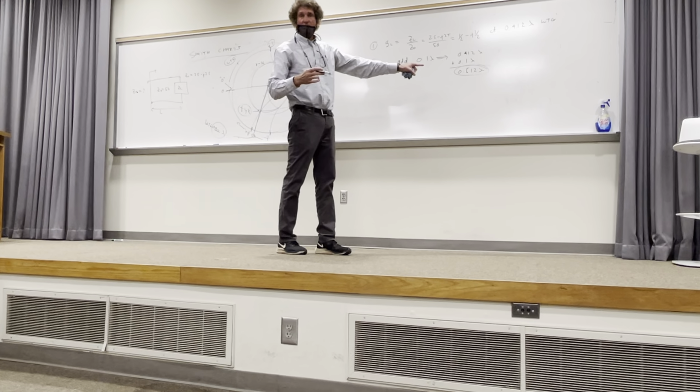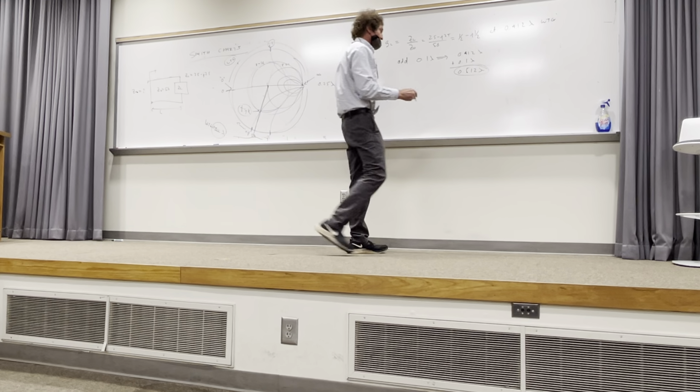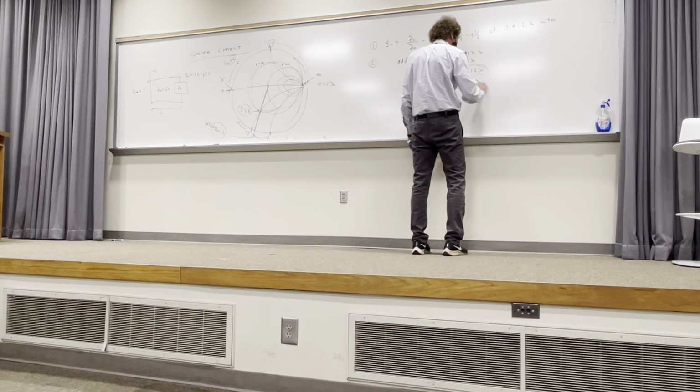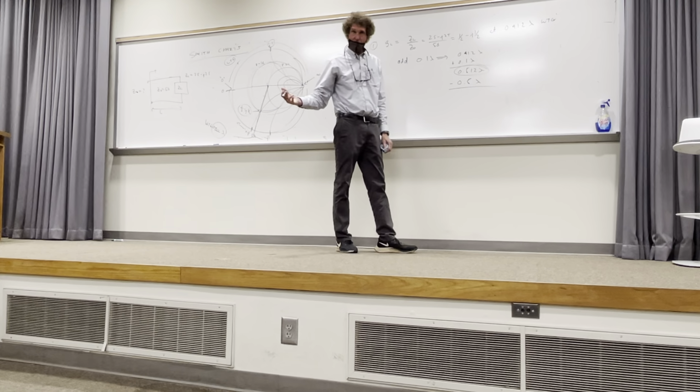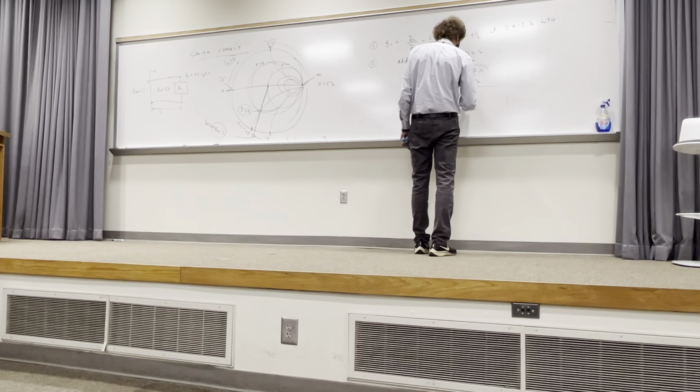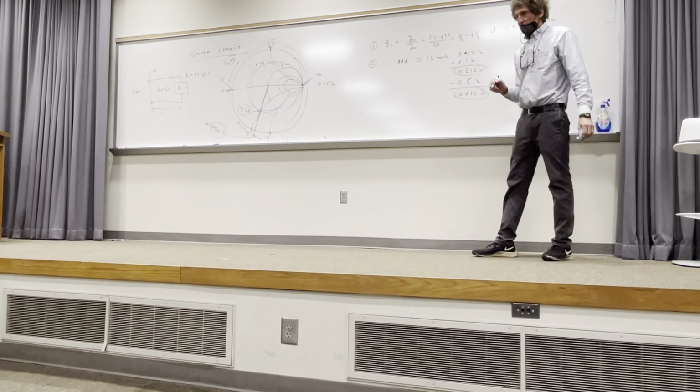So anytime you have a value after you added any distance from the load that is greater than a half wavelength, you subtract off the number of half wavelengths required to get this between 0 and 0.5. So now I simply subtract off 0.5 wavelengths. That would be 1 half wavelength, right? And now I get the point 0.012 lambda. Can you all follow me on this?